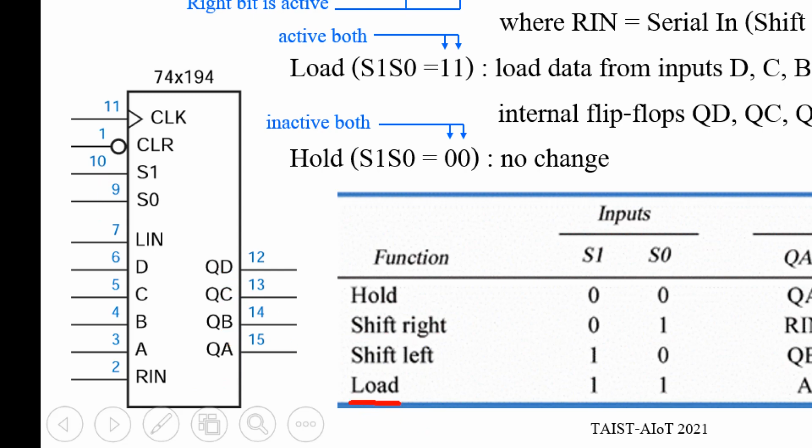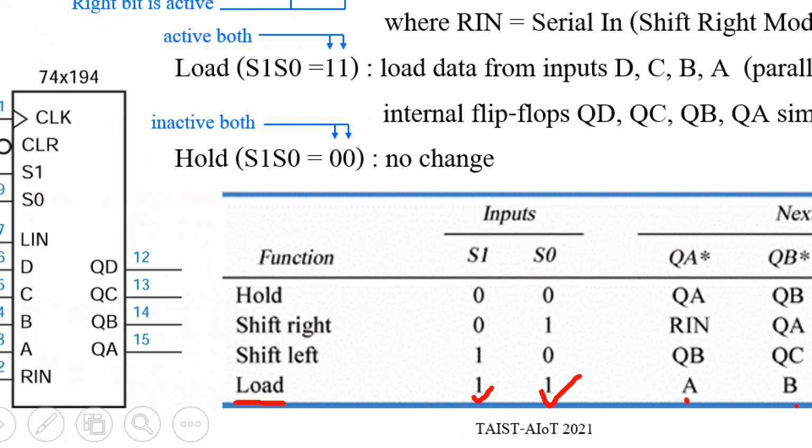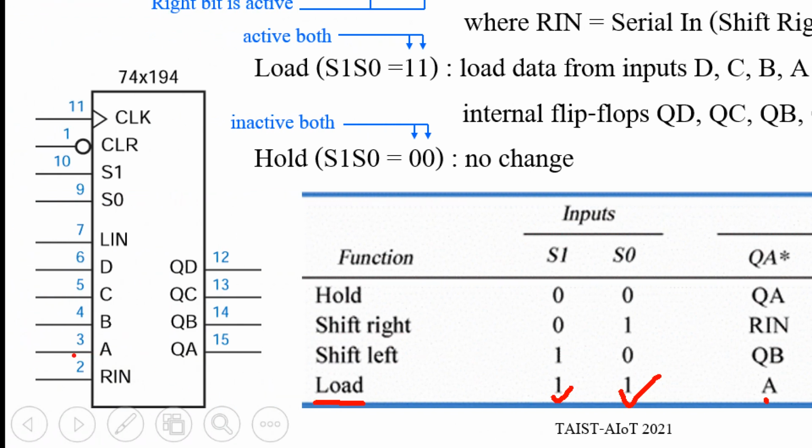And for load function, you apply 1, 1 to S1, S0. The data will update with A, B, C, D, namely from external inputs A, B, C, D.